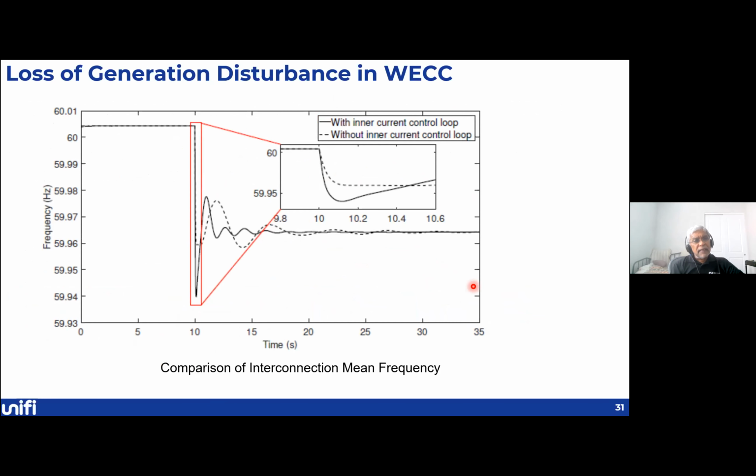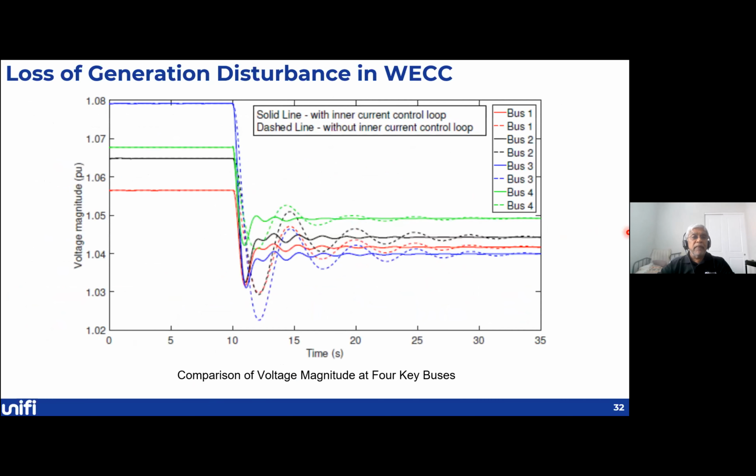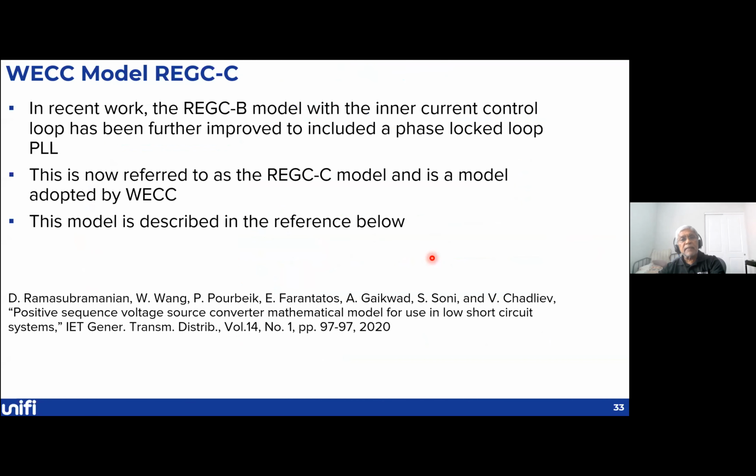And then again, you see we in fact get much better frequency control than we had before. And the voltage magnitude after the significant drop, we are able to control into much tighter limits. And this model that we developed with the inner control loop